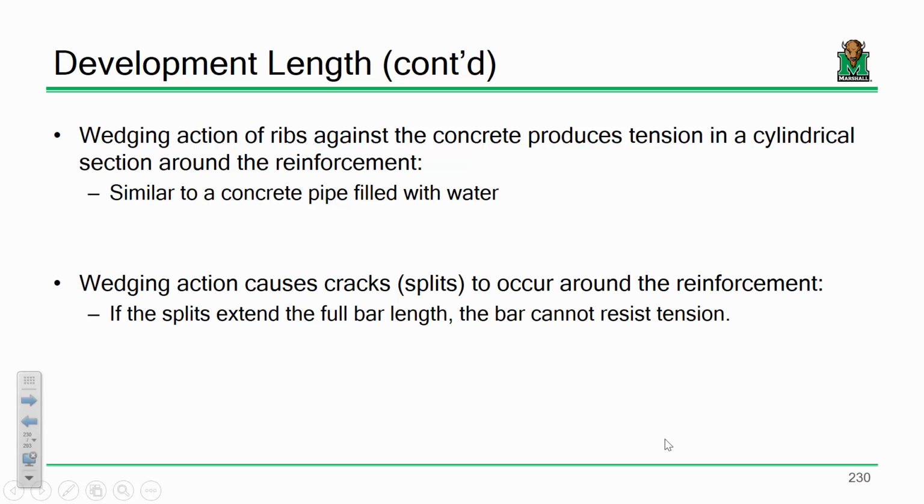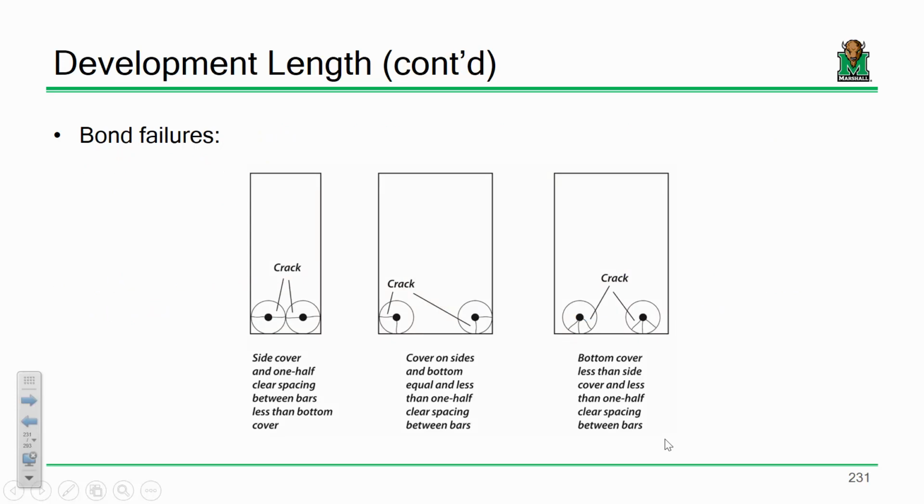Well, if you start yanking on it and you start looking at the failure of the concrete, it starts to fail in kind of a cylindrical fashion. You'll start to get cracks that jut out, almost in a cylindrical fashion. And that failure region will expand like this.